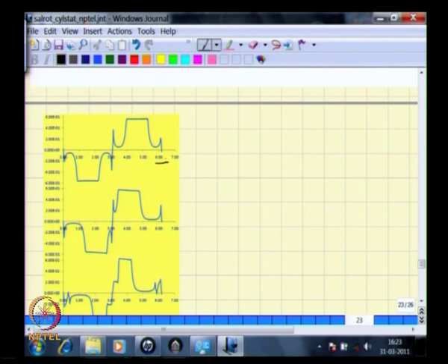The x axis indicates the circumferential distance travelled around the inner circumference of the stator, the y axis denotes the modulus of the normal component of flux density. So let us just call it as B.